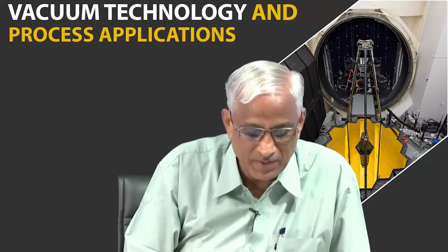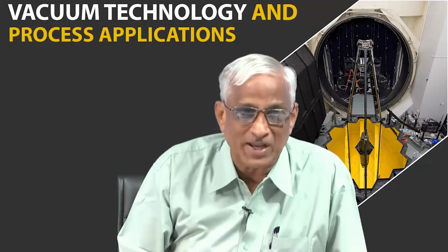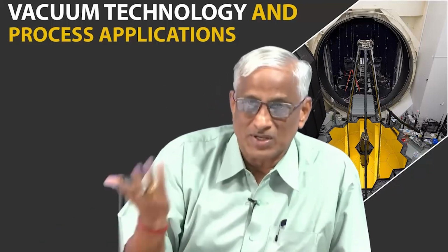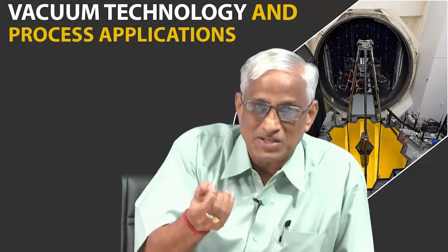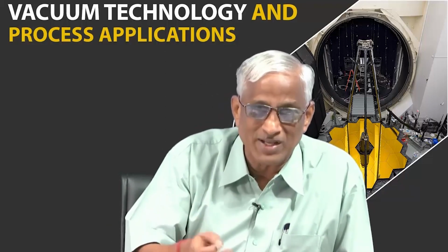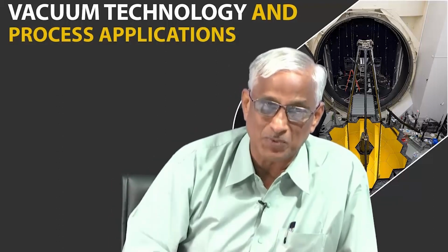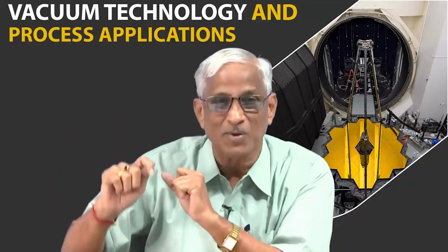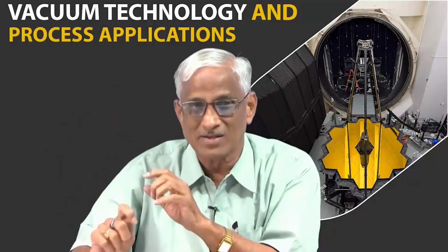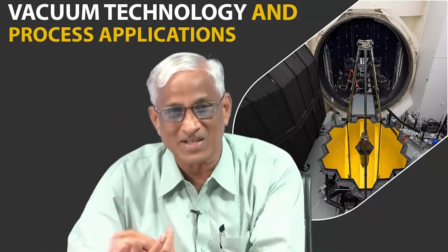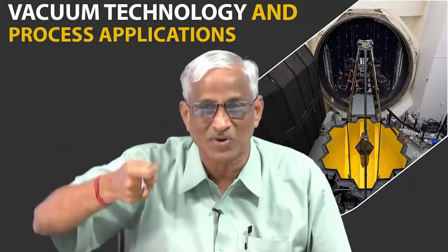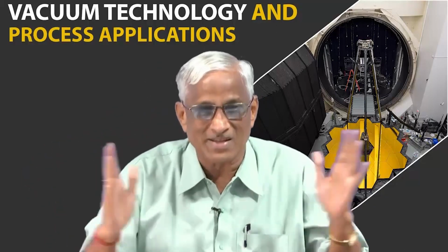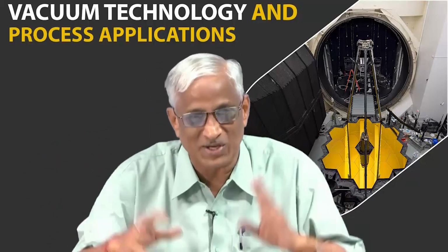The simple methods we have explained in the leak detection section, you can go to that section and understand. Purging can also be used to clean in a dry way the existing moisture, impurities or particulates and remove them. Then you will start getting improvement, you may get 10^-6 torr. So, these repair works should be done from 10^-2 to 10^-6. Up to 10^-2, tighten properly and do air blast operation, because you need not tighten again more and more. Once it is mechanically stable at 10^-2 torr, it will be stable at 10^-6 torr. You will not get any other extra pressure.